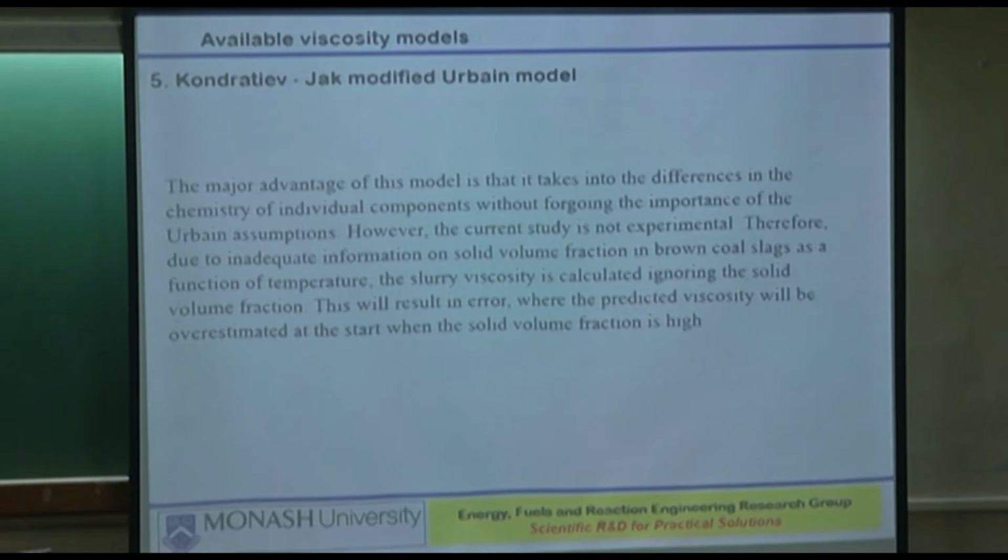It only tells you, take it to 1450, it will become liquid, but definitely it will not become liquid immediately. It will be determined by the time and how much of it is there. If it is only a tiny bit, then it will immediately become liquid. But if it is this much, it will take a long time to get rid of all the solids. So initially, the solid fraction could be high, depending on your circumstances. If that be the case, then it will be overestimated.